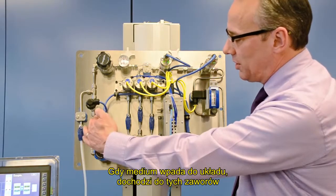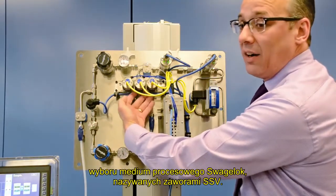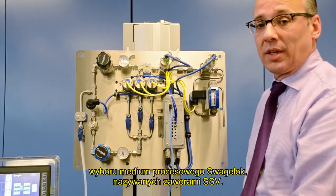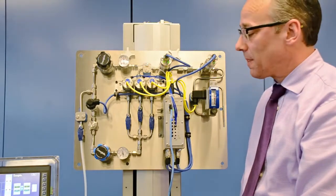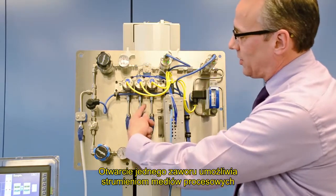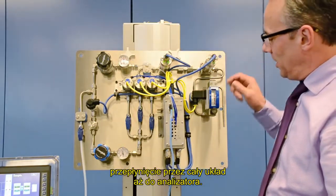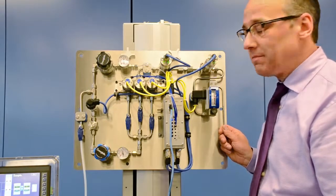As the stream comes in through this system, it ultimately makes its way up to this bank of valves that we call the Swagelok Stream Selector Valves, or SSVs. Opening one of these valves will allow one of these process streams to ultimately flow through the system and make its way to the analyzer.